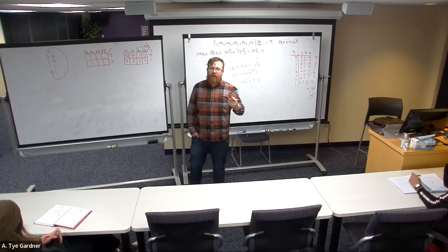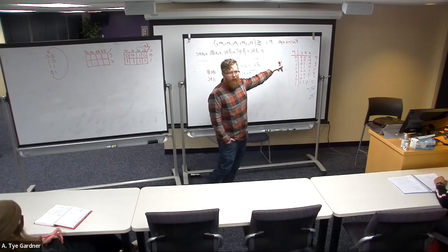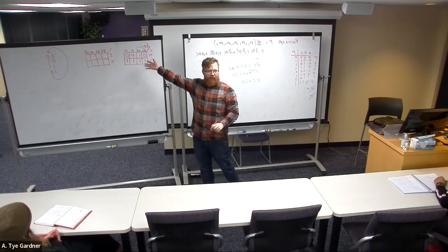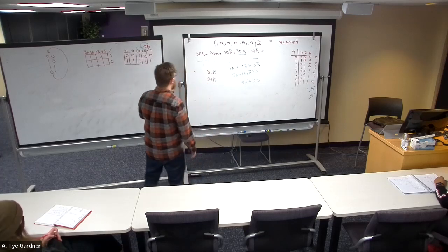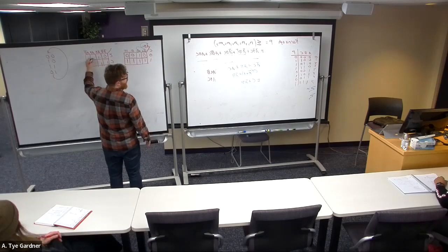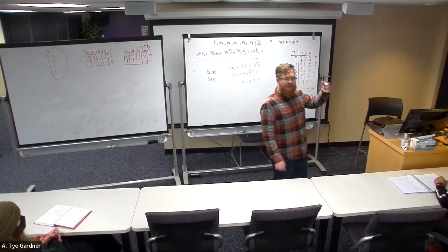Yeah. So once you write these in the right order, when you map it this way to that version of the K-map, then all I have to do, one second, I'll get right to you, is look at the row and just say it is 0, 1, 1, 1, 0, 1, 0, 1, and I just go down the row. I don't have to think about what every row is.